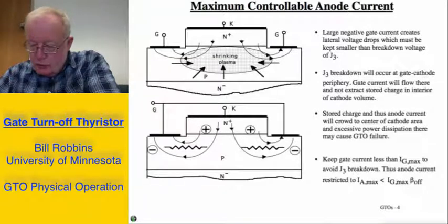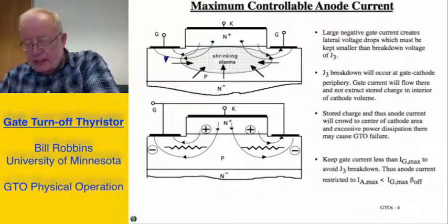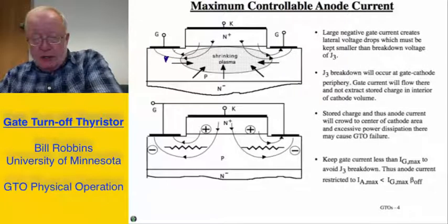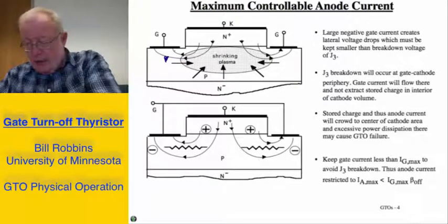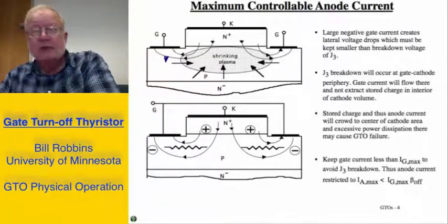One of these two current paths is indicating negative gate current, and the negative gate current then is pulling out excess carriers from the excess carrier density that we have in the base region of the Q2 transistor. And by doing this, we are interrupting the flow of current to the Q2 transistor, and thus making the base current less than what is needed in order to keep the transistor in saturation.